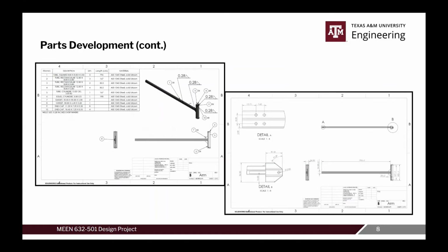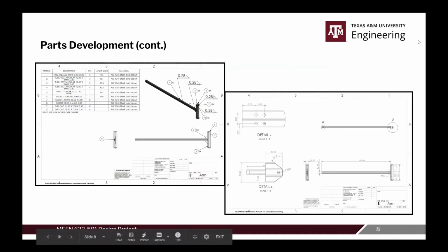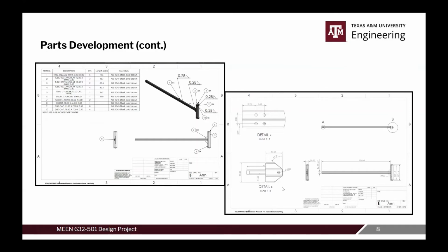The pivot arm was also created using the SolidWorks weldment. The main function of the pivot arm is to connect all 3 of the other main features, so the base, the launching seat, as well as the seat that acts as the counterweight. The seat is connected at this point here by these 4 1-inch bolts, and the counterweight is connected at this U-joint on the other end. The pivot point occurs closer to the U-joint than the launching arm, approximately 1/4 of the way across the arm.